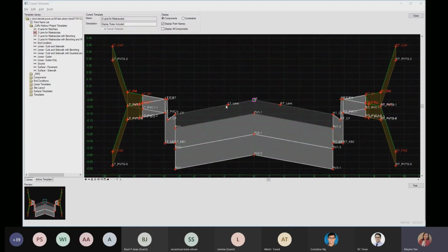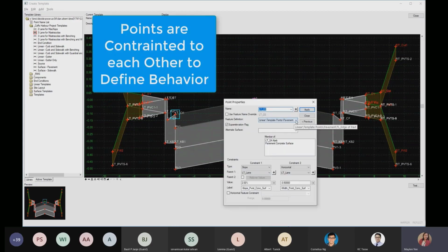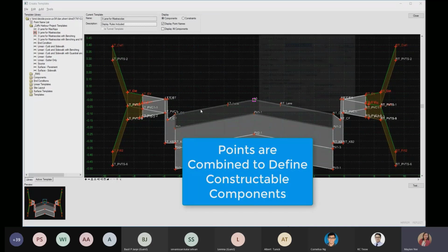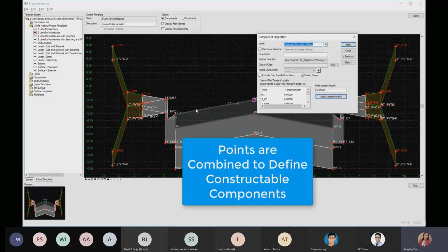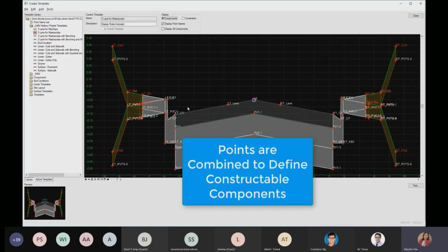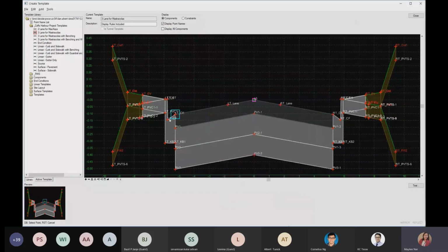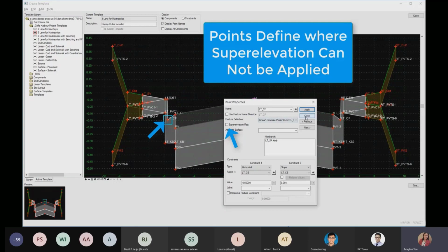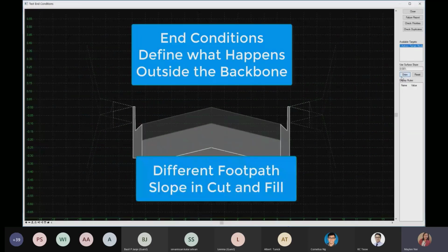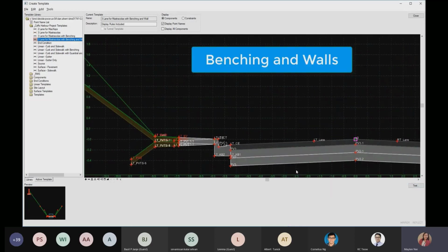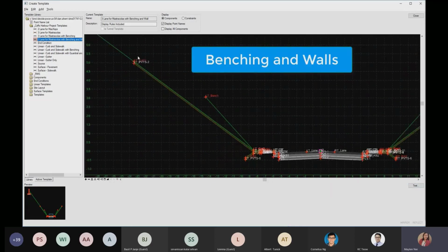Although you probably have a similar GUI or way of creating your corridors in MX, with OpenRoads Designer it's easier for you to create relationships from the points of your templates. When I say templates, these are your cross sections, which could be typical or not so typical in terms of the type of corridor you're creating.